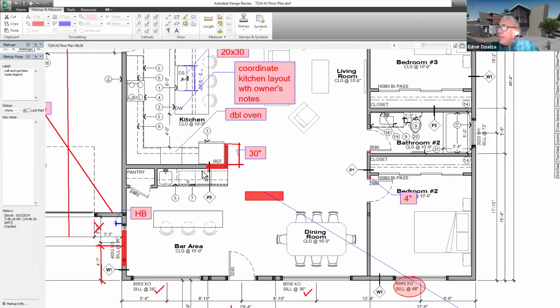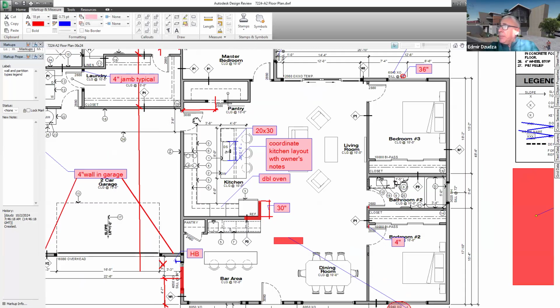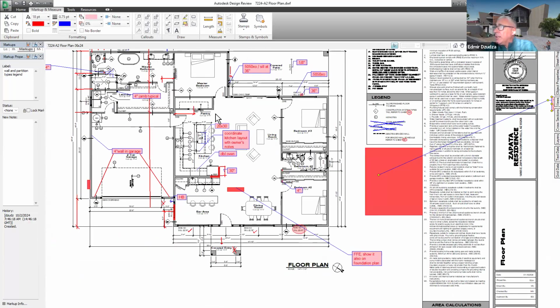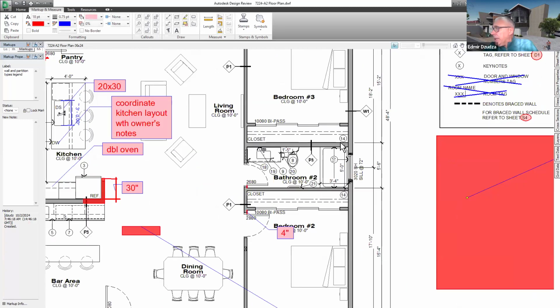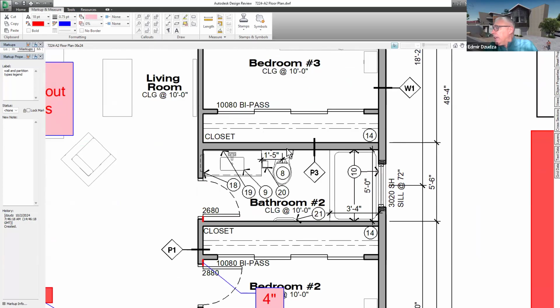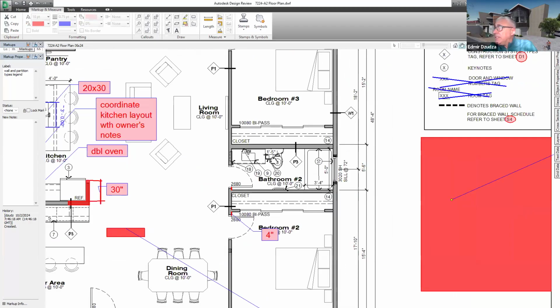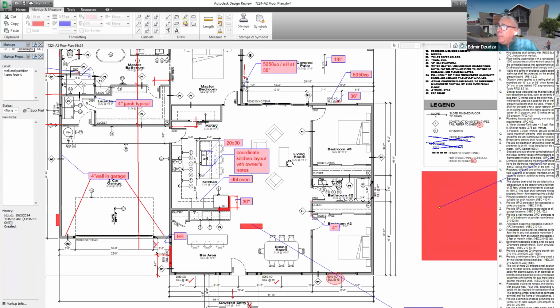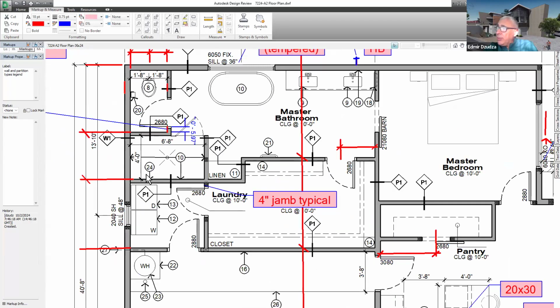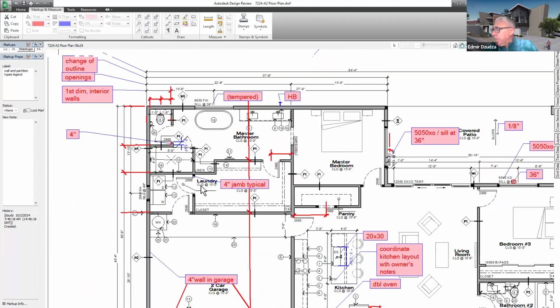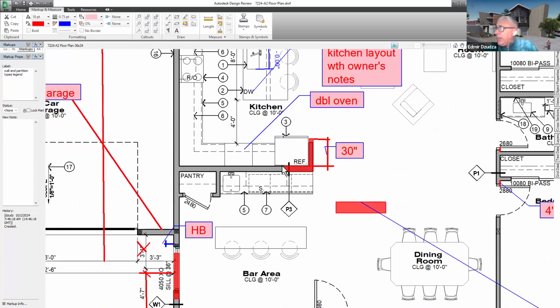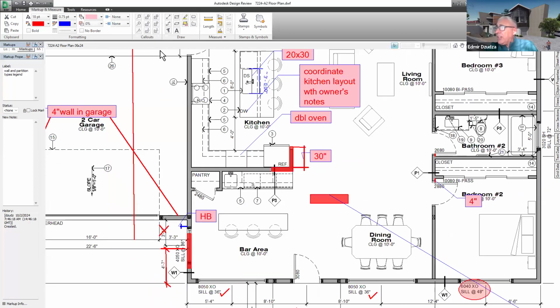and then where we have, I don't know which one is P3 because, yeah, obviously plans are still not to that level, but typically we have plumbing wall. That's any wall where we have a toilet, and it has to be 2x6, has to be a 6 inch wall. This one is an exterior, so we don't need it. So I'm not sure why this is wall P3 because perhaps sink, but this wall can actually be 2x4.